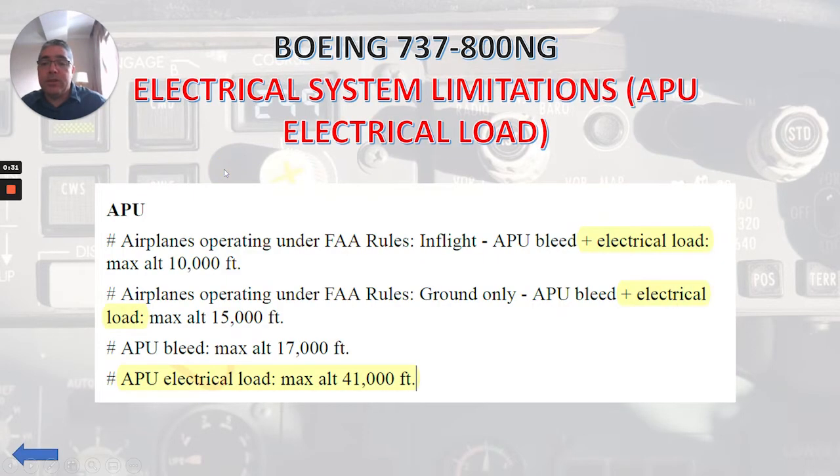All right. So let's start talking about what we can find in FCOM 1 about the APU electrical load. They talk about the APU bleed as well, but I just highlighted here what is related to the electrical load. So airplanes operating under FAA rules, in-flight APU bleed plus electrical load, maximum altitude 10,000 feet. Airplanes operating under FAA rules, ground only, APU bleed plus electrical load, maximum altitude 15,000 feet. APU bleed max altitude 17,000 feet. And here is what we are talking about, APU electrical load, maximum altitude 41,000 feet.